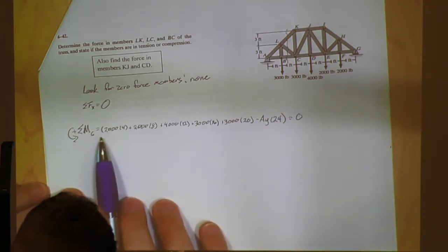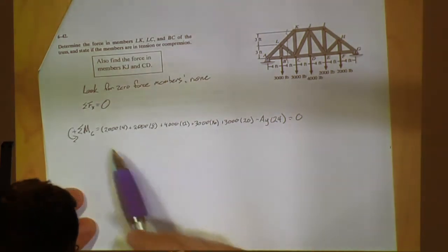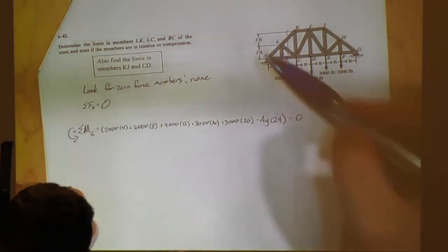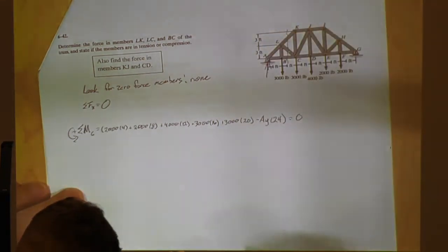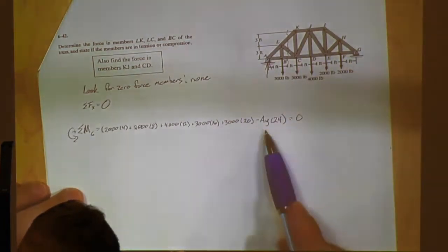And we're going to say all of them are pushing down in the counterclockwise motion, so they're all positive. But our reaction force default is pushing up, so that's going to be clockwise, so that's negative. Questions?